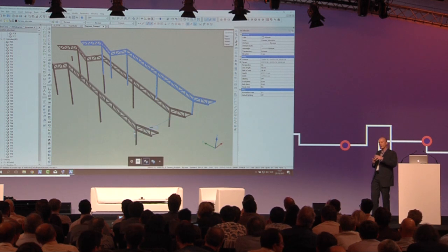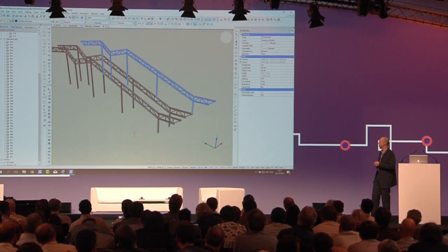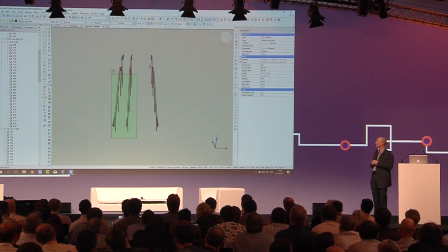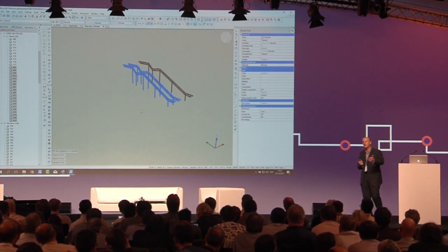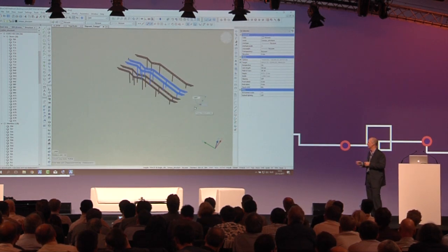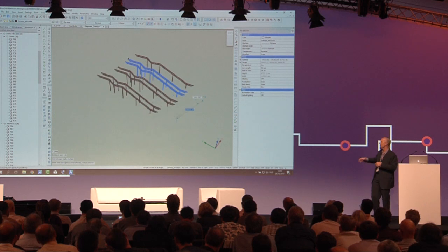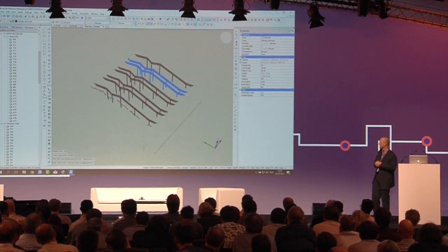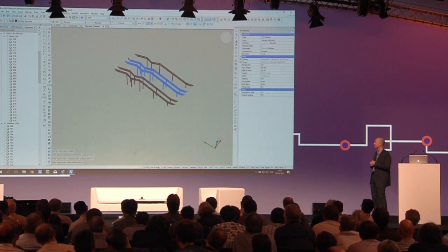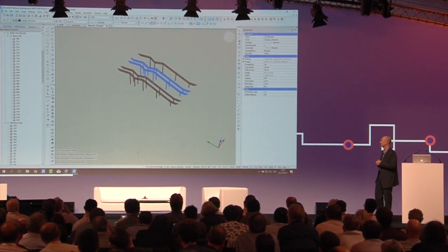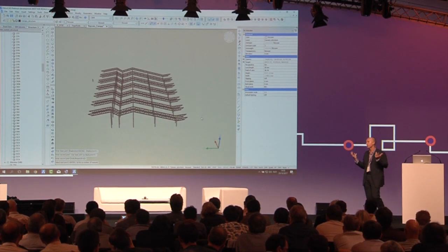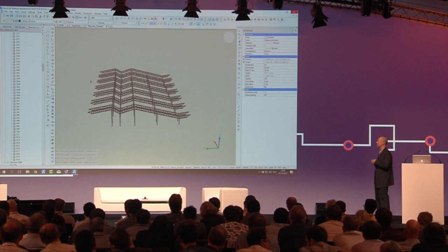And then we can do a second copy to make the module that we're going to use for setting up the structural bays. And then if we select those two, we can then use repeat copy to span it across the width. By dragging the cursor in the direction we want, we can get multiple options of this until we've got what we need. So pretty quickly we have all 13 truss members and the columns.